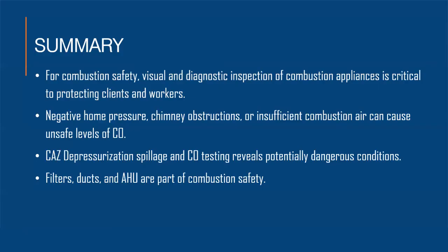In conclusion, it's important to make the connection between building performance, air sealing, and combustion appliance safety. And that combustion safety includes both visual and diagnostic inspections. Second, there are lots of things that can contribute to unsafe levels of carbon monoxide, including but not limited to negative home pressure, blocked chimneys and combustion appliance venting, and even insufficient combustion ventilation air.